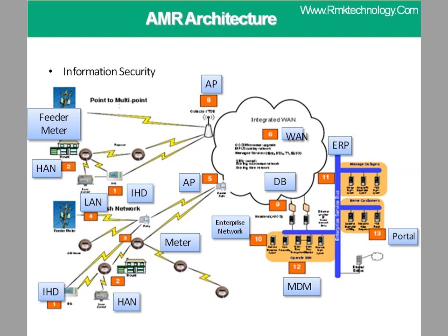This slide depicts various communication channels used in smart metering solutions. Field devices are connected to dedicated networks through wired or wireless communication. Radio meters are connected to remote data collectors which collect all the parameters coming from the meters as telegrams. A telegram is the set of parameters configured in meters which need to be transferred to application systems. These include values like different types of readings like kWh, kVAh, kW, meter temperature, battery life etc.